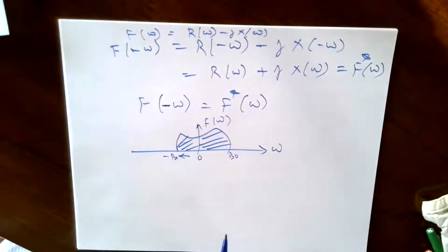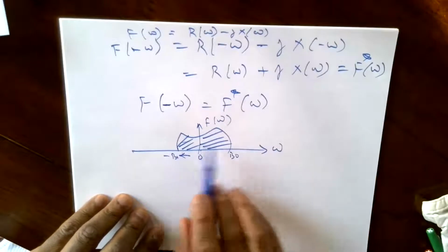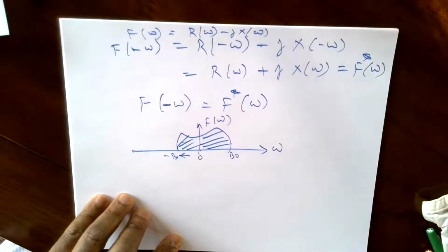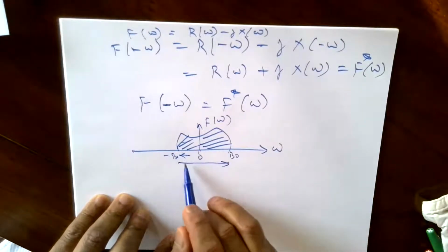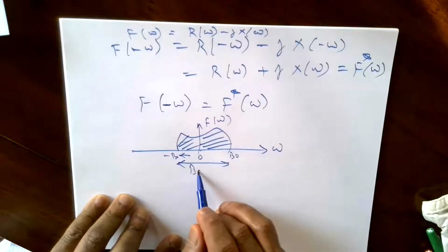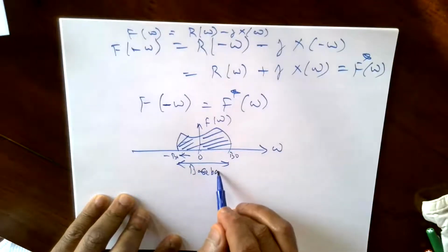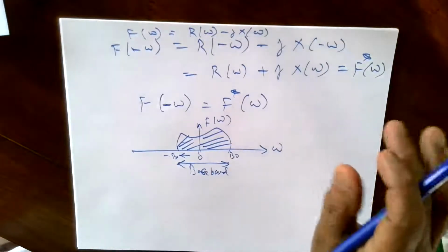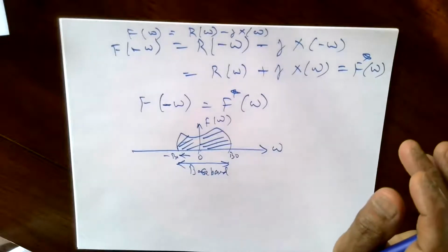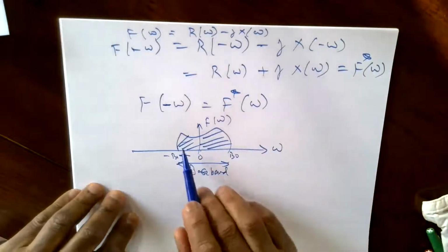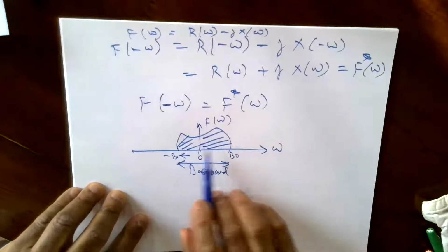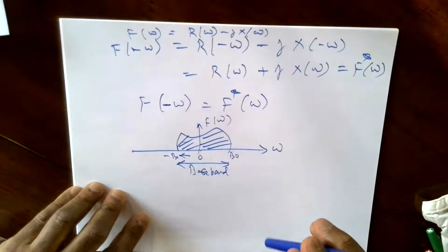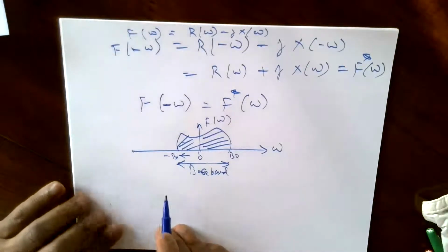All right, now what is modulation? Modulation is where you transfer this information to a different frequency for transmission purposes, because this is usually called baseband, whatever hangs around the zero frequency. And if you transmit even audio or anything at a low frequency, the propagation losses are very high. So you want to make it as if it is at a higher frequency, where the transmission losses are less and less. That method is modulation.